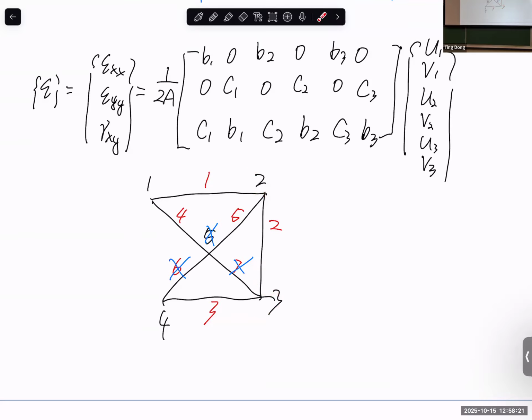And then I define node set 2. I put these 2 in one set, and I say, okay, constrain the displacement in x and y. So in the Abaqus input file, it says put this as a node set and say boundary condition constraint 1 and 2. 1 means displacement in x direction, 2 means displacement in y direction. So for this simple case, it does not change much.